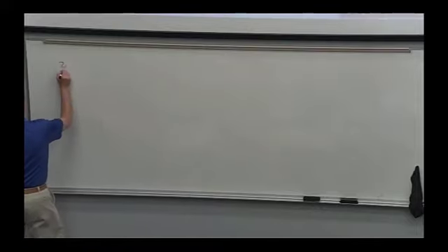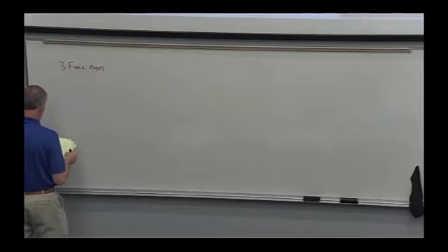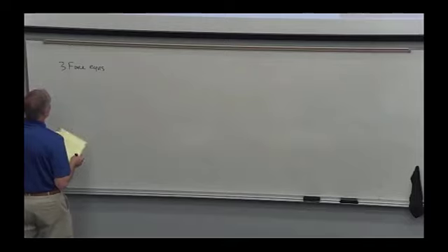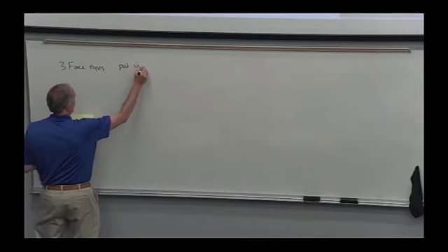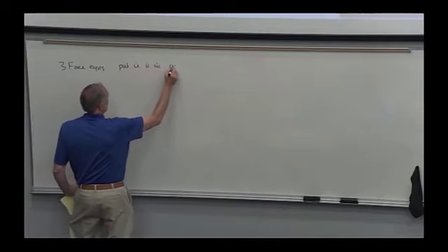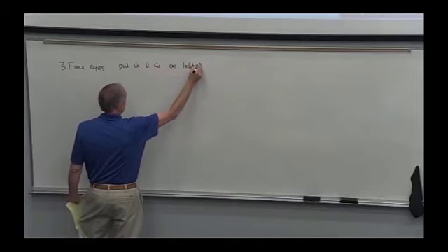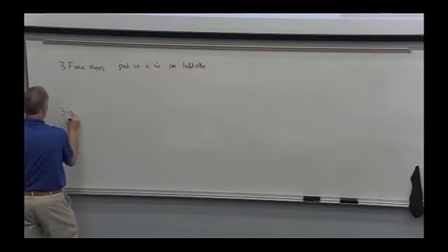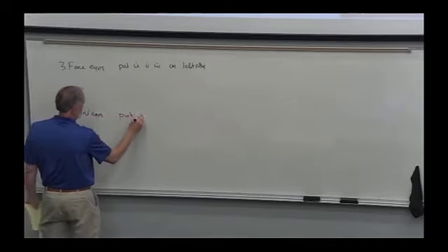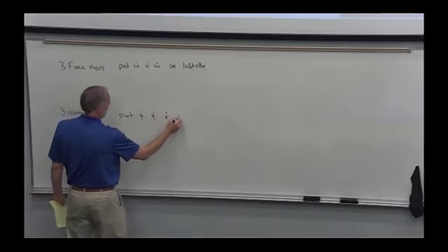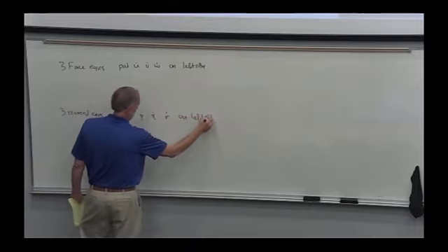So if we take the three force equations, and we put all of the dots on the left side, and if we take the three moment equations and we put P dot, Q dot, and R dot on the left side, it's just rearranging.